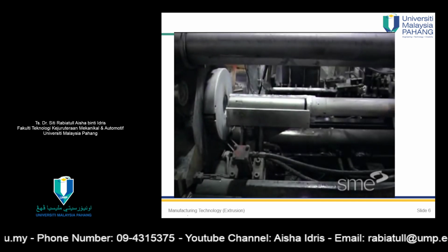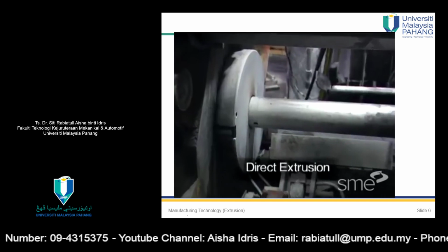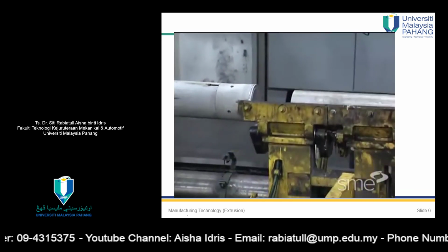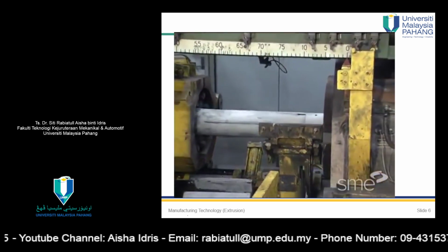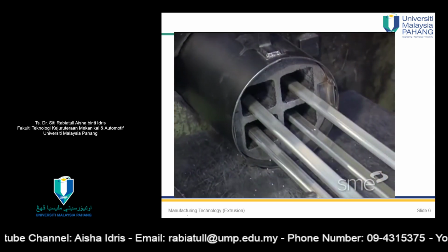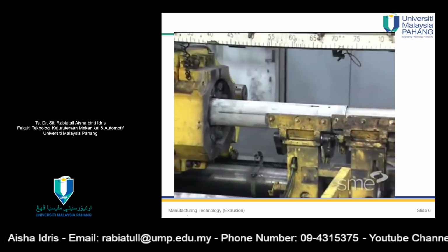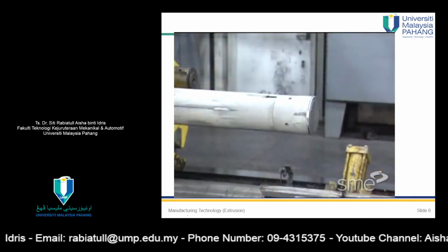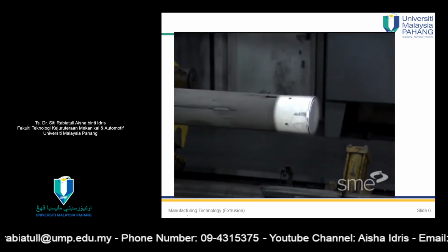The primary type of hot extrusion is direct or forward extrusion. In direct extrusion, the hot billet is loaded into a thick wall container and forced through an extrusion die secured in a holder. The force for extruding is applied by a ram along with an intermediate reusable dummy block.